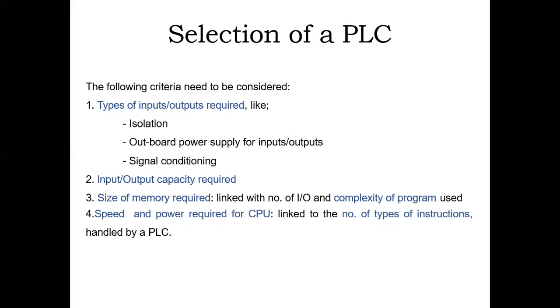Then the power supply requirements of the devices, because most of the input and output modules do not require 230 volts. If you are using a PLC with 230 volts, it may affect the systems, so we need to define the power supply consumption. So the first one is the types of input and output required, that is isolation, and output board power supply for input and output ports.